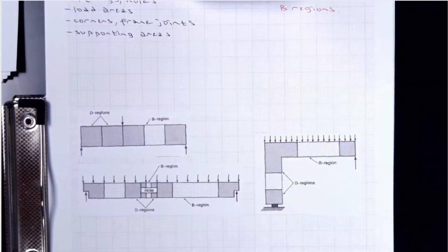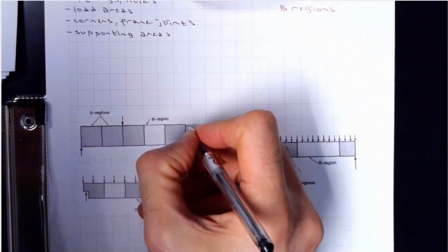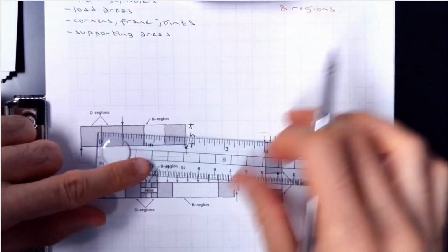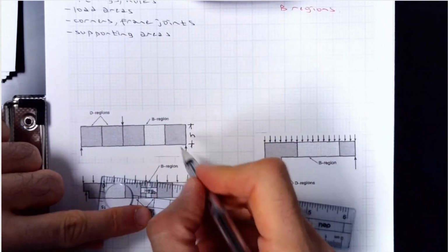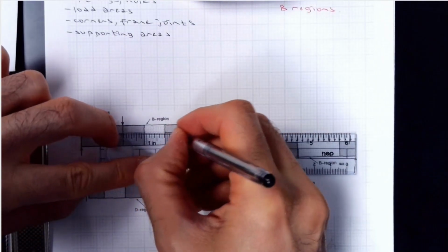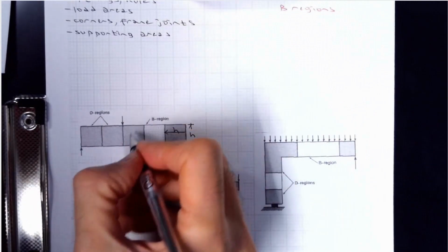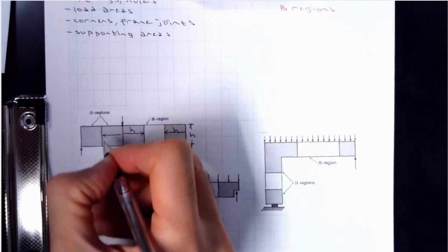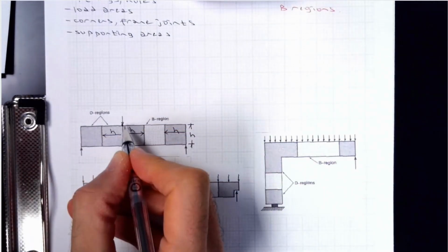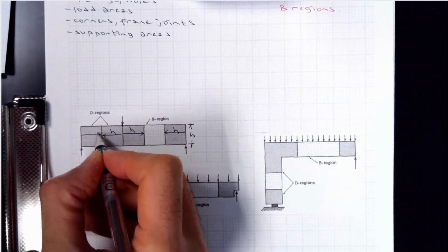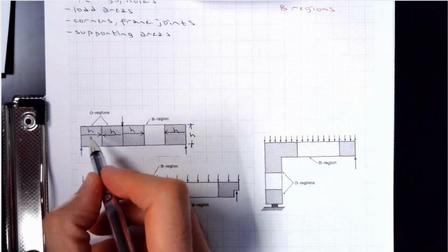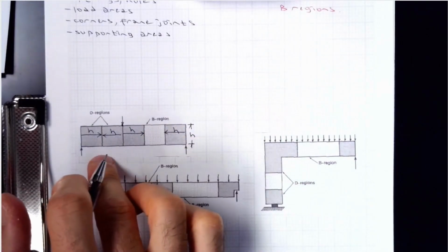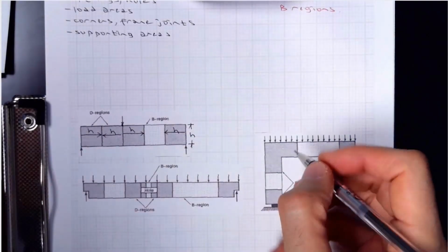If you look at this example, again, you would determine this is h, right? Again, you see the point load. You would go h away from here, you would go h away. That's the point load application point, h away. It might overlap. So for example, in this shear span, you don't have any B region. That happens. The entire span is a disturbed region. In this span, which is a longer span, you have some B region. So it's possible you have no B regions in the system, right?